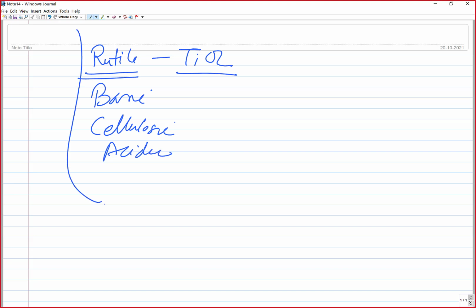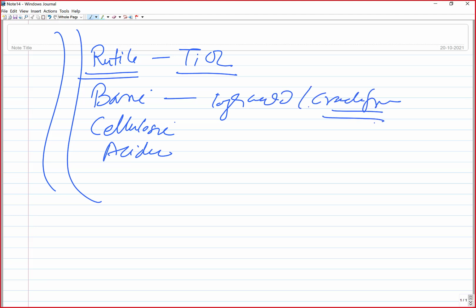These are the four most common types of coatings. For tough, crack free welds, the basic coatings are used. For all common purposes, rutile and cellulosic coatings are used.